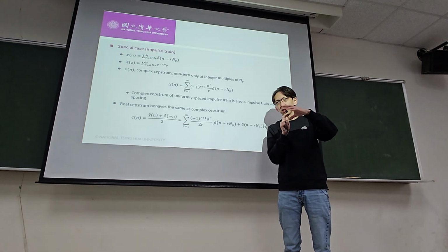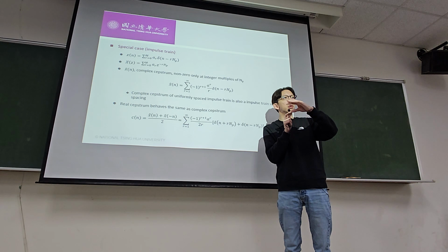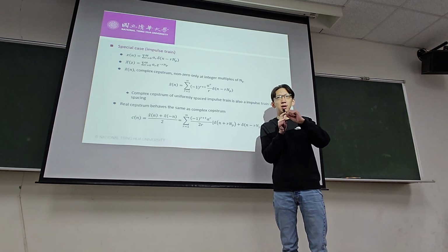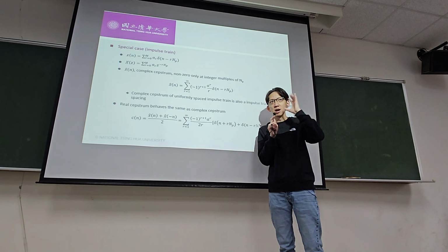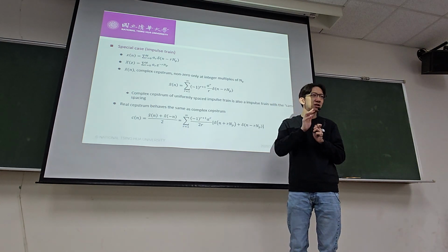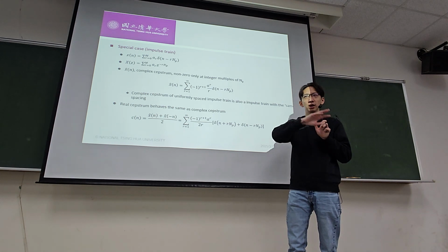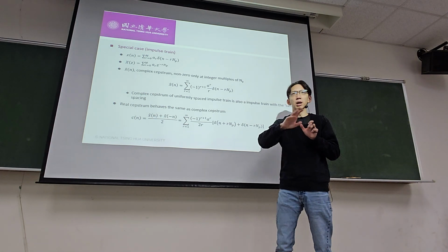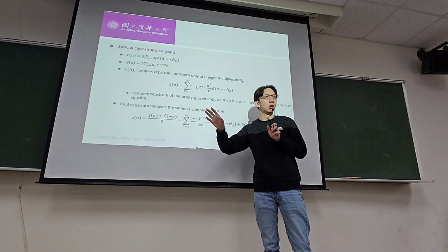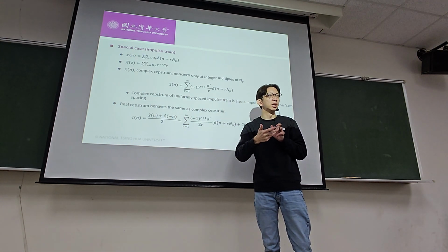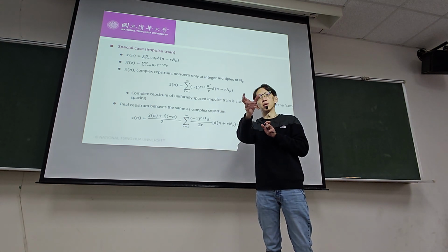It scales the value of the magnitude, so that whatever signals in the frequency domain were originally multiplicative become addition, and that's the only thing. Think about it outside of speech processing. Let's not think about speech. Pick any signal, take a z transform or a Fourier transform, take a log on the magnitude, then do another transform. Supposedly you are getting back the original time domain signal, but the only thing that's been changed is that particular log operation.